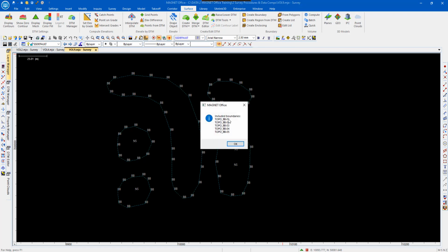And it's got the 5 different boundaries as listed in there. You can actually have these boundaries or coded names around there, and lines with individual names depicting the actual stockpiles. Could be sand, rocks, rubble, whatever. So it becomes easy to spot which volume is which.